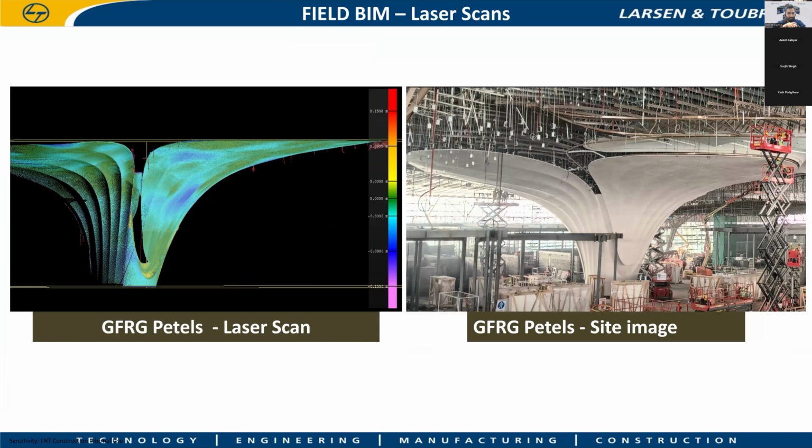Yeah, this kind of complex geometry profile we can also laser scan with the SX12. But how accurate is the SX12? Yeah, that is why it will generate the heat map and compare it with your design model. It will sense how far it is accurate, as per the discrepancy between your design and construction, in terms of identifying the undulations and any profile changes at site.